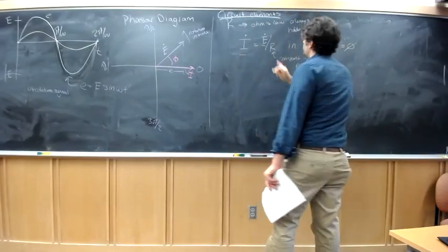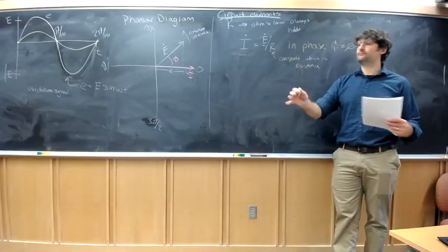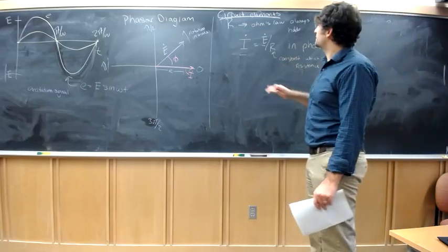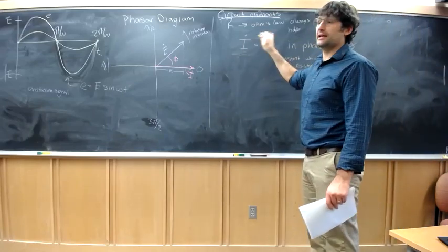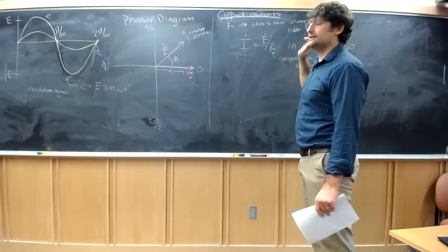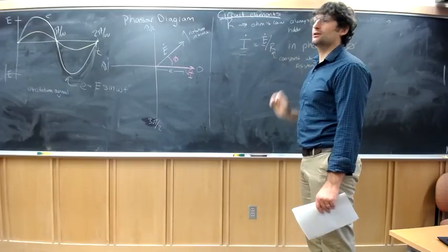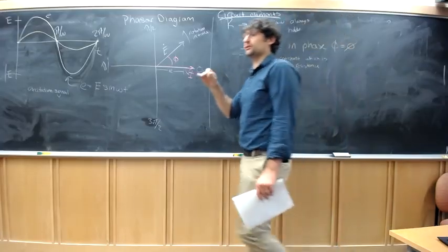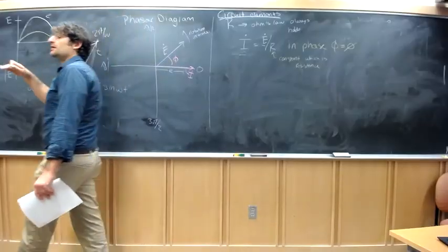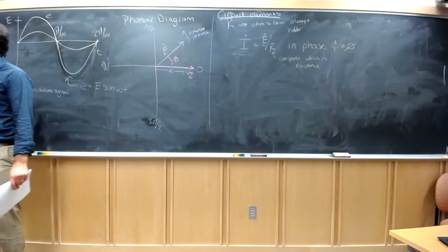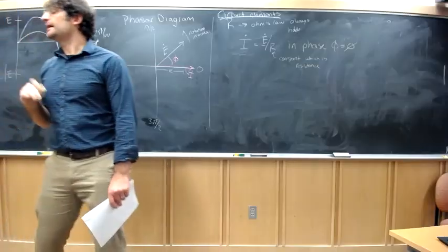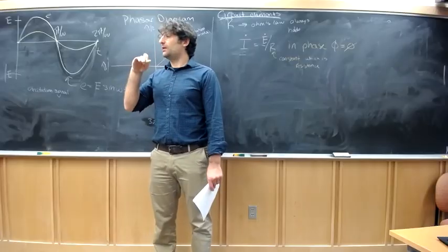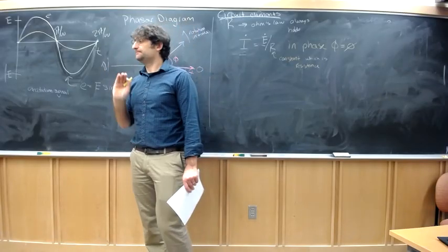Now, in an electrochemical cell, the value of R might actually depend on your applied DC potential and things like that. But in general, R is going to be a constant in this analysis. These are the vectors, the phasors, I guess, that are describing the signal modulation and the modulation of the current response. There might be some DC current that's flowing too. In this analysis, we're just measuring the modulated current. And so we have electronics that can pick up the current response at a given frequency.